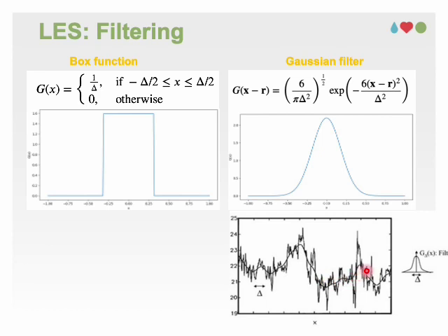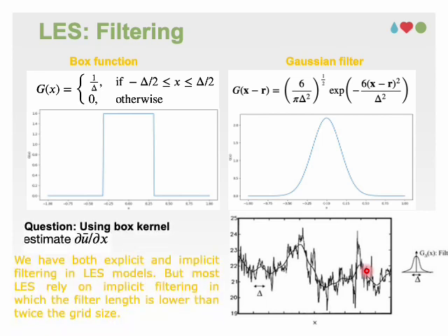Filters can be applied in large eddy simulation explicitly or implicitly. By solving this equation here on this slide, you will learn how the large eddy simulation applies the filter implicitly based on grid size and finite difference operator. Now, let's dive into the meaning of implicit filtering.